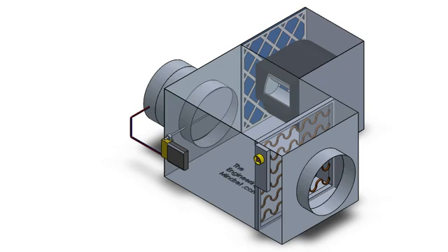So we've got the filter here where the air from the space will be coming back into and forcing in through this fan into this chamber, and that will then mix with this as the damper opens, and so the cold air and the warmer return air from the room will be mixing in here, and that can pass through the heater battery if required and off into the zones. And that's useful because the fan will keep a constant volume coming through the box. So if you imagine as that damper closes, then less air volume will be coming through. So the fan will ensure that a consistent volume is coming through that box.